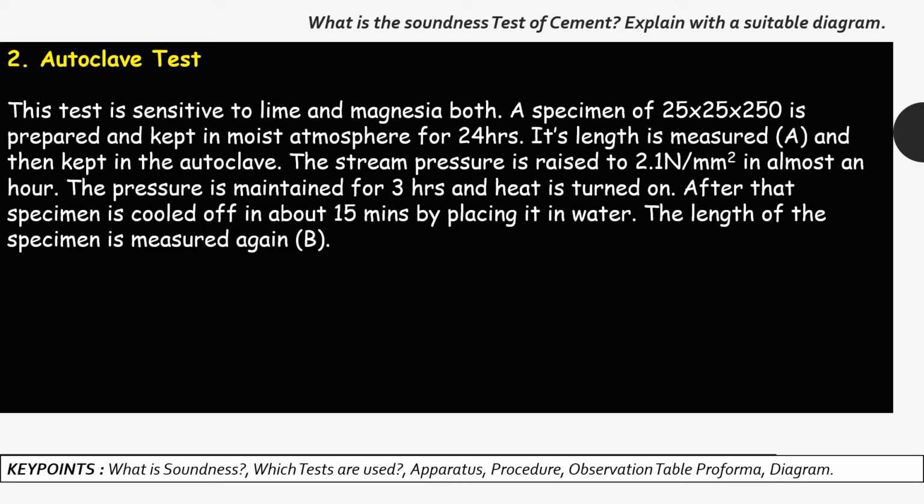I beg your pardon. It is 25 by 25 by 250 mm, I guess. Well, anyway, its length is measured, which is A, and then it is kept in the autoclave. The steam pressure is raised to 2.1 Newton per mm square.